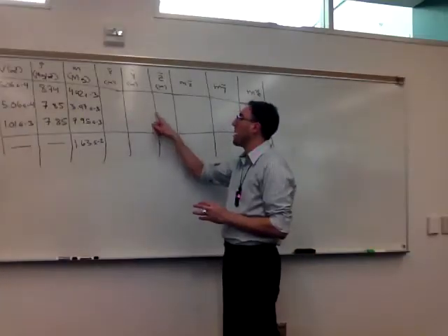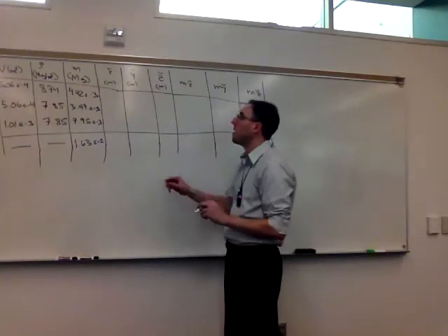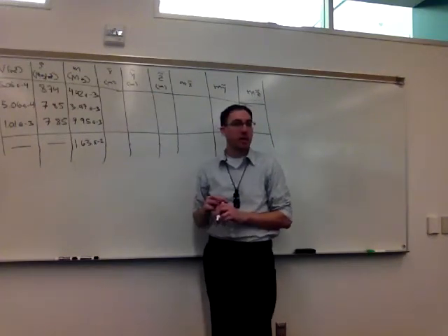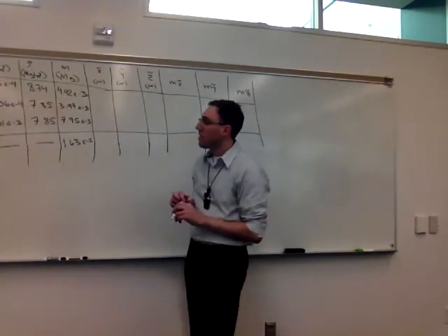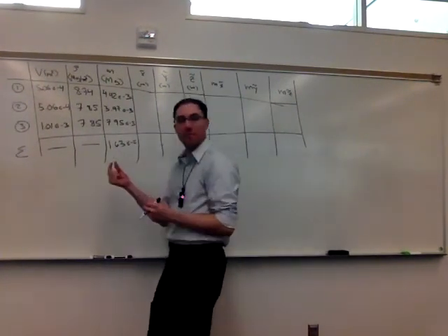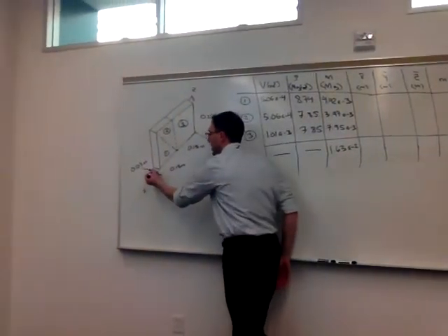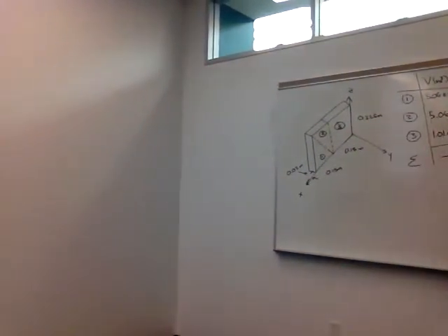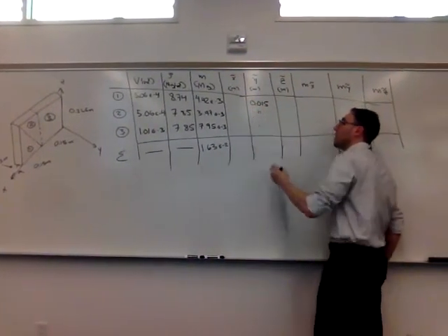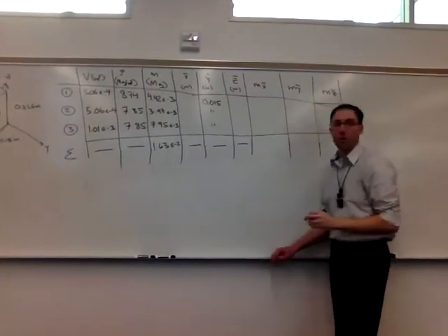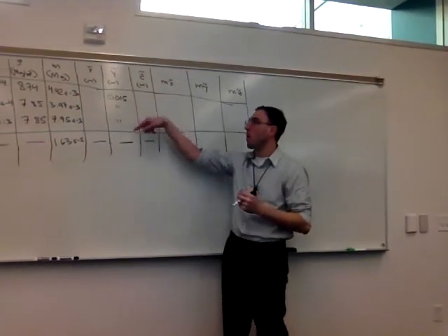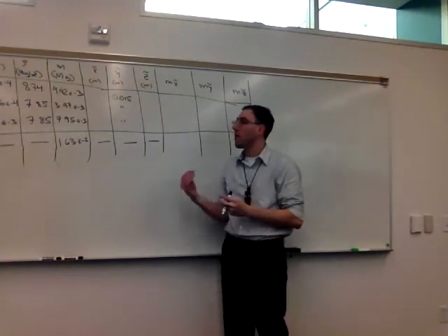All right, so now we have to worry about, this goes back to just the geometry of each shape. Let's start with actually the easiest one. What's the y tilde of all three of our shapes going to be? Right, it'll be half of the thickness. So they all share the same thickness. So the centroid in the y direction will be half of that. So 0.015 for all three shapes. If they had different thicknesses, there'd be more work involved in calculating this individually, but they all have the same thickness.